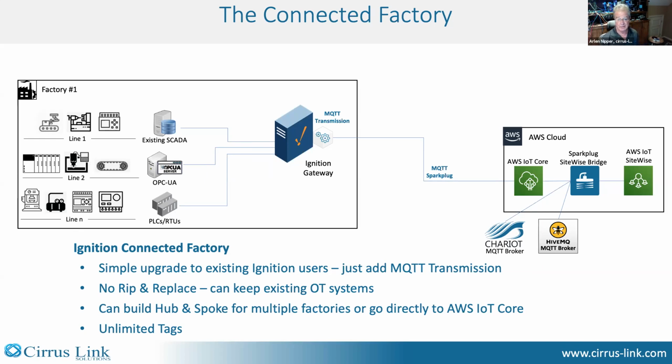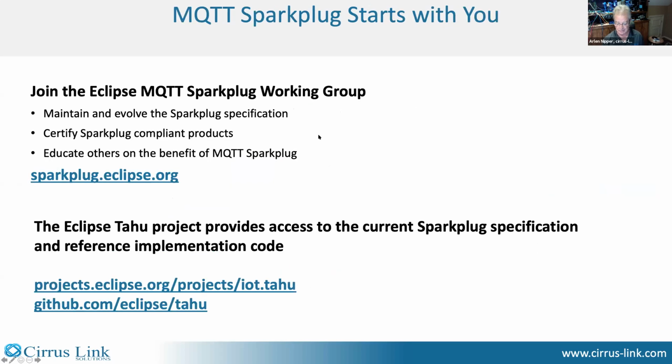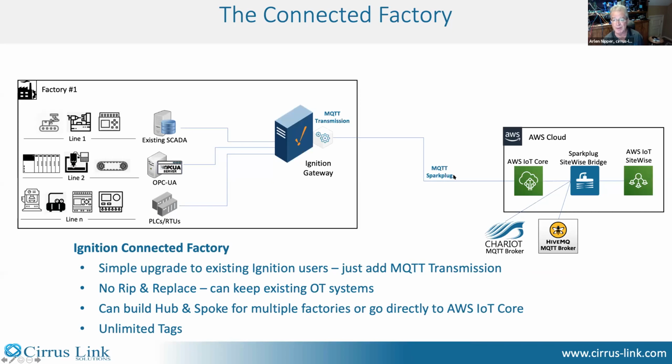So imagine me being able to go to a factory and in just a couple of minutes, all I had to do to get all of my model, assets, tag information with its engineering units, with its attributes, modeled in Amazon Cloud Services is simply the configuration of an MQTT connection, using MQTT Sparkplug to publish my birth messages that contain my model, that contain my asset, and then from there on out, using data messages to publish report by exception and have all of that information end up in the time series database on SiteWise.